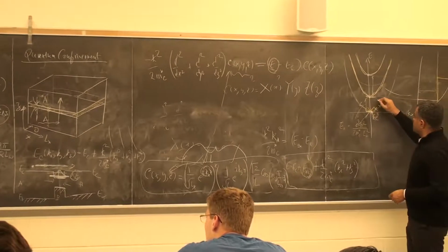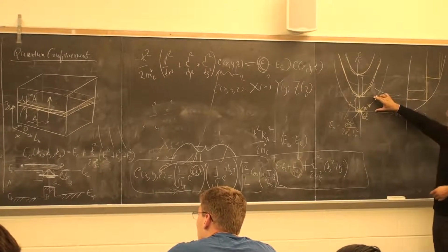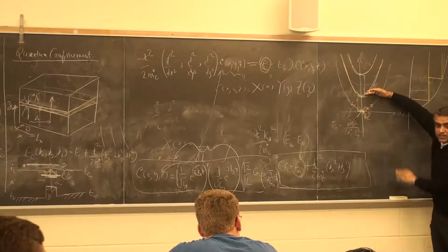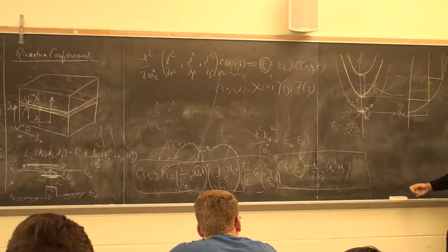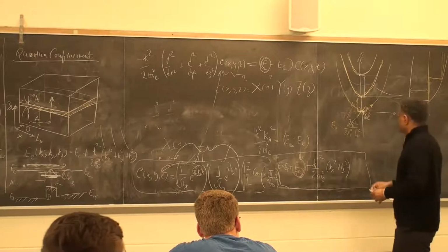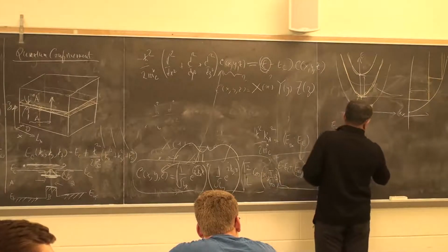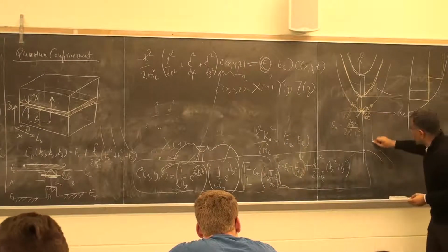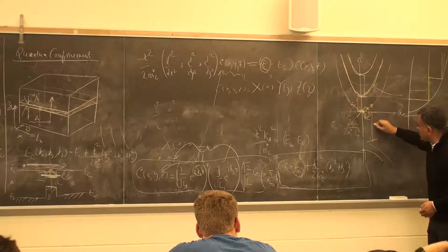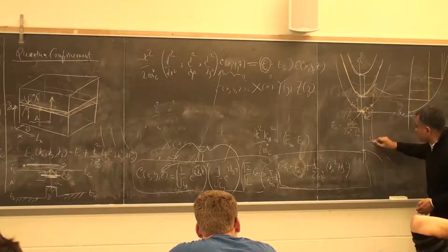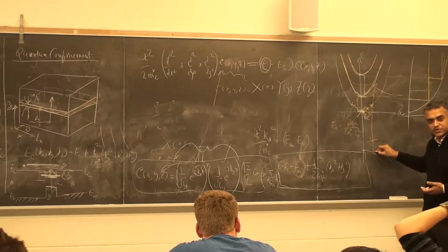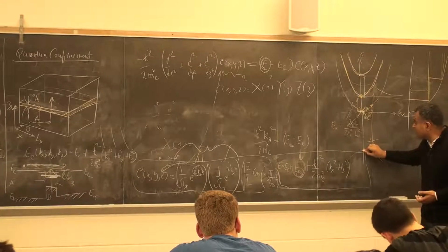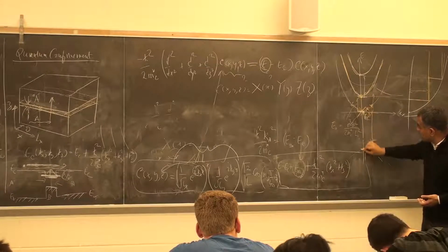Neither is this, neither is this. You basically have created an artificial gap now. And so the conduction band minimum has shifted up to here. In exactly the same way, if you reflect this around, for the valence band you'll also have subbands. So you have the natural band gap of the material of region B, plus quantum confinement energy, plus quantum confinement energy. This is your new band gap now: the minimum electron energy here, and the maximum electron energy in the valence band is here.